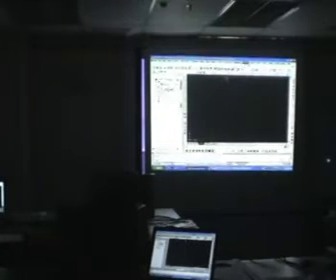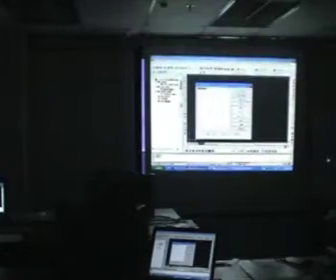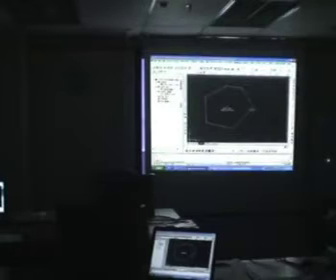And this is very unique also because they have a Parcel Manager, meaning if let's say this is gone, like okay, I've lost the drawing or I accidentally erased it from the drawing, it doesn't mean all is lost. You can still call it back from the Parcel Manager. You can see parcel 1's here. You just click import and it will appear again.